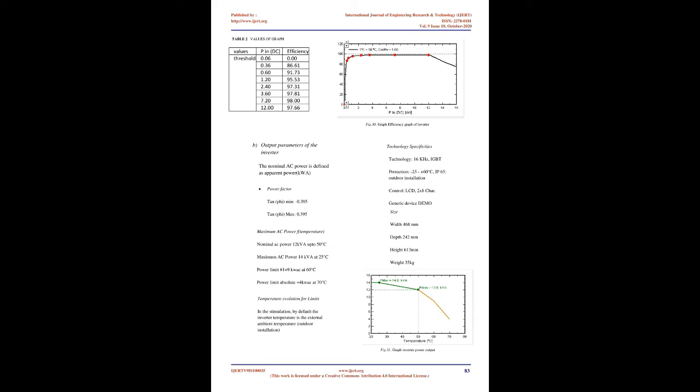F. PV module model, graphs. In the PV module definition dialog, the page graphs shows the general behavior of the model. You can display the following sets of curves. Current vs voltage, often named I/V curves. Power vs voltage, often named P/V curves. Efficiencies as a function of the irradiance. Efficiencies as a function of the temperature. These plots show sets of parametric curves, i.e. for different irradiances, temperatures, series resistance or shunt resistance.